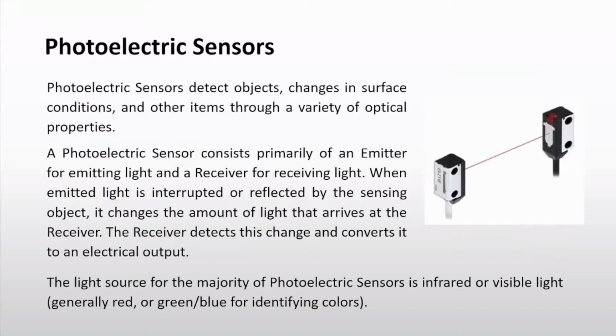Those are named photoelectric sensors. Actually, we have to consider these photoelectric sensors under the category of motion, position and proximity. Normally, in a photoelectric sensor, there is an emitter and a receiver. Think of one side as the emitter and the other side as the receiver. One emits a light beam and the other side receives it.